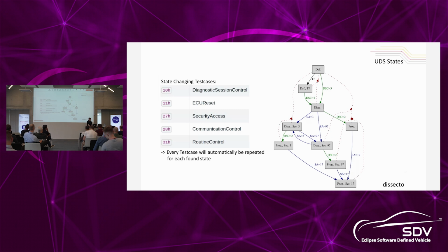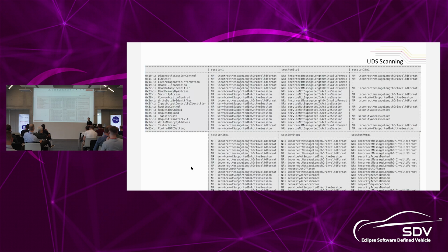In the next picture, I have an example of what the scan output looks like if you just add diagnostic session control to the scan. And here you will see we get different answers in different states. The most prominent thing is always the bootloader, so session 2 will have drastically different answers than any other session. Also, the interesting thing from a security perspective is not session 1 and session 3, it's session 2 and the proprietary sessions we see that are used non-standardized, and where we can then start looking.